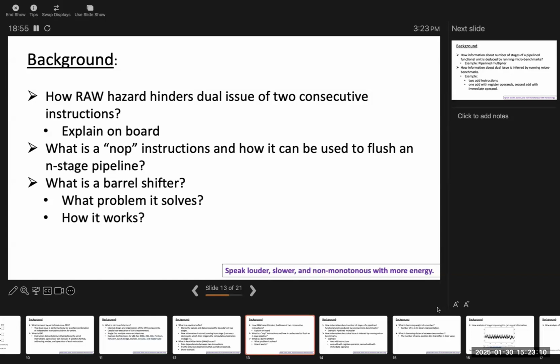When you say stuck in the buffer, it basically means that the instruction is occupying this particular stage. Stuck in the buffer means that its data and signals are stored here and they are affecting the combinational logic in this particular stage, executed by this combinational logic or logic layer you have. So I want to clear this buffer. How can I clear it? If I put all zeros here. And NOP does what? It puts all zeros. So by applying the NOP, you're basically just clearing out the stage.